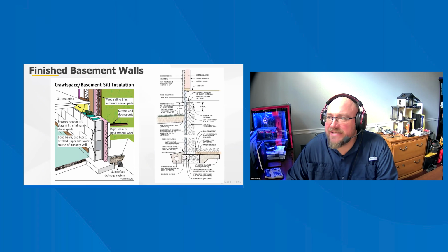The approaches for insulating and finishing basement spaces vary depending on whether you're dealing with new or existing construction and whether a basement is being only insulated but not finished. Exterior insulation that uses foam insulation panels on the outside of the foundation wall is commonly installed for new construction and is difficult to evaluate on existing homes.